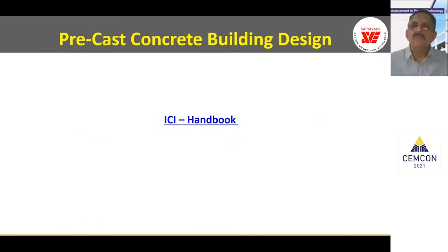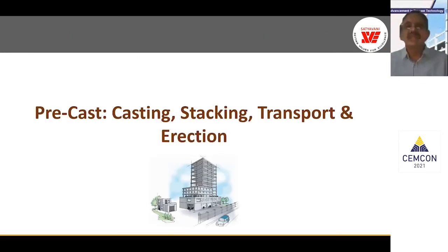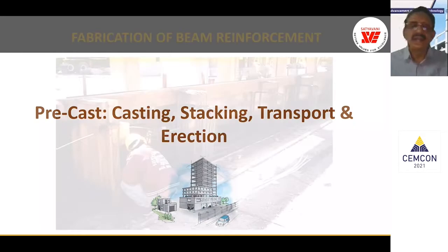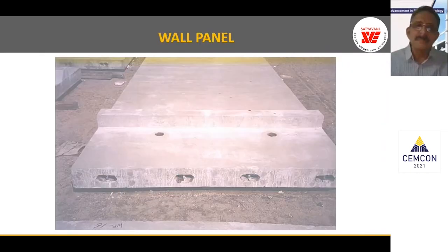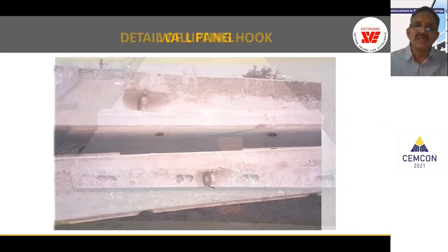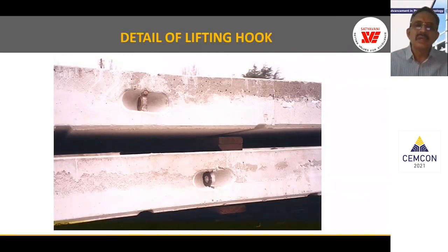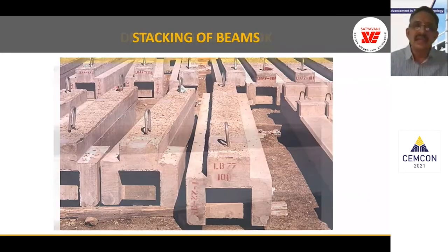Next, the ICI handbook, as I mentioned, I really appreciate ICI for bringing out this handbook almost 9 years back itself. Next is the casting, stacking, transport, and erection. Casting is like any conventional casting but off the site, tying the reinforcement with handling hooks and wall panel stacking. You can see here the handling hooks for lifting and handling.